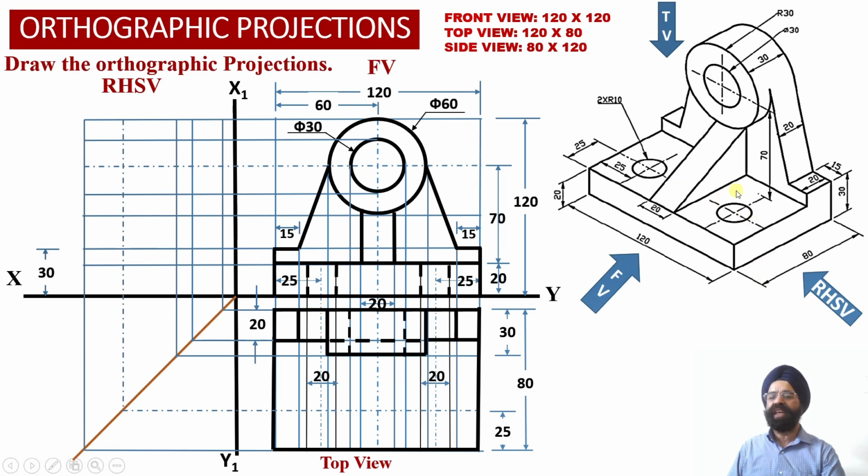And another thing, now we can check corresponding to this circular hole which is used to support a shaft over here. This circular hole will not be visible to the observer from the top. So corresponding to this diameter of 30 millimeter, we have been able to obtain hidden line projections into the top view projections over here, dotted line or hidden line projections.